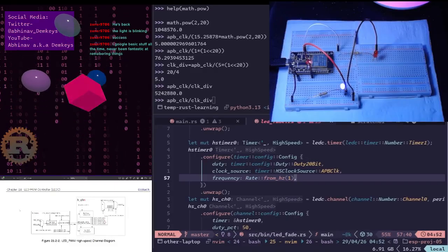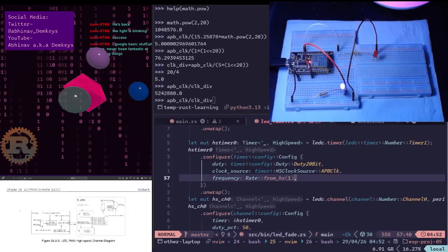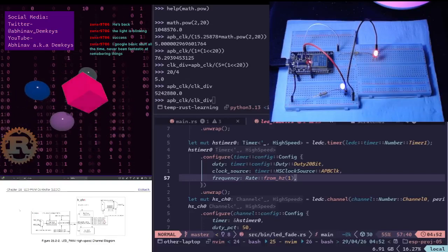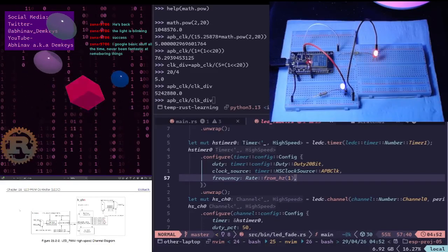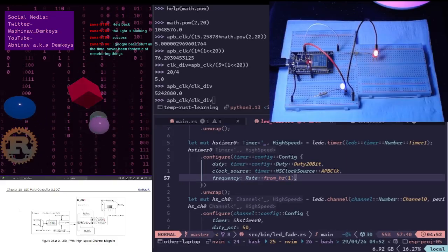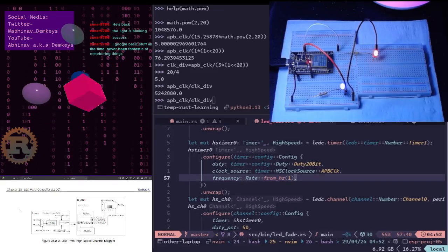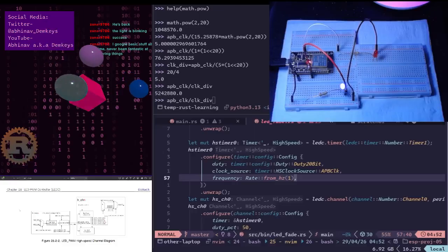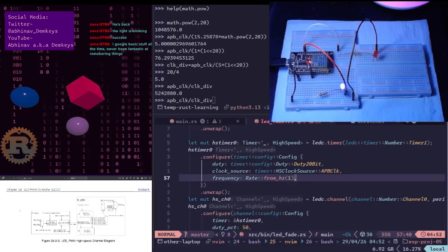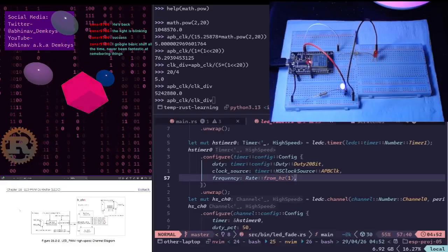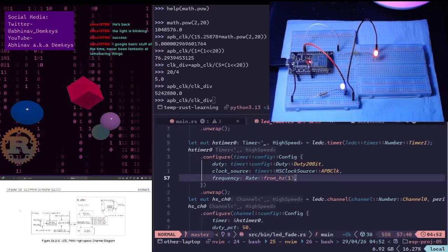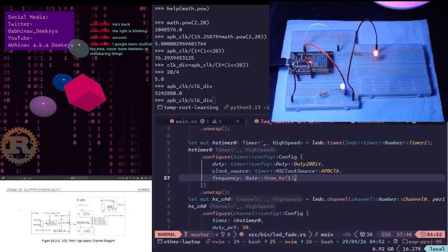Then the fractional part. Since the ESP32 LEDC divider is 18 bits, it includes an 8-bit fractional part, 10.8 or 14.4 format, depending on the version. Since it uses an 8-bit fractional part, it can't just count to a fixed number. To achieve a frequency like divide by 10.5, the hardware uses a sigma delta modulator or a dithering technique.